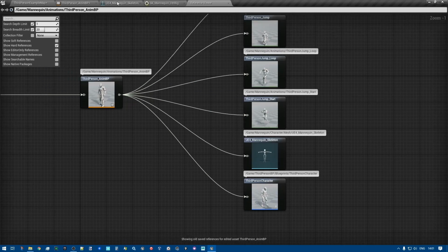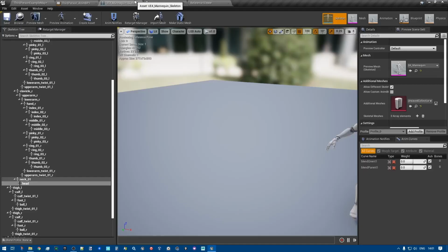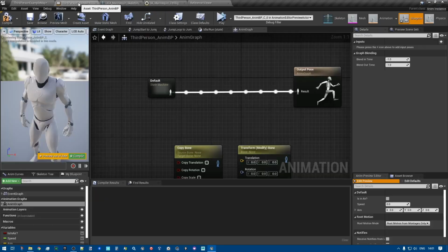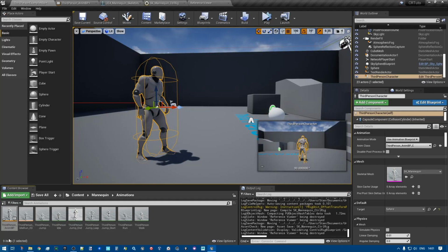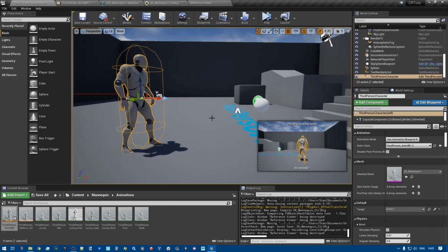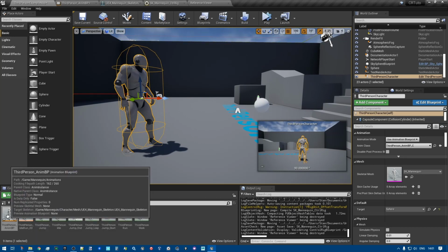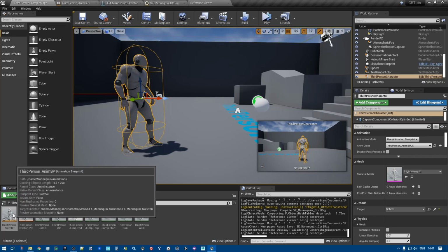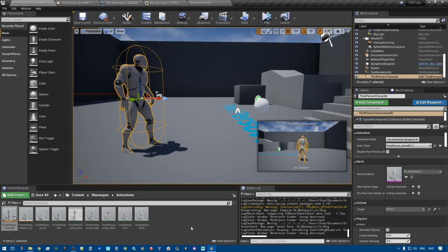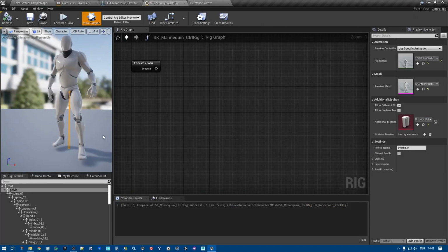So as I said before, if you made some complex Anim Blueprint for one skeleton and you have another mesh with another skeleton with probably mostly minor differences, nothing relevant to your Anim Blueprint, you cannot just take and reuse it. No, you have to copy it and recreate another Anim Blueprint. With control rig this kind of dependency is removed.